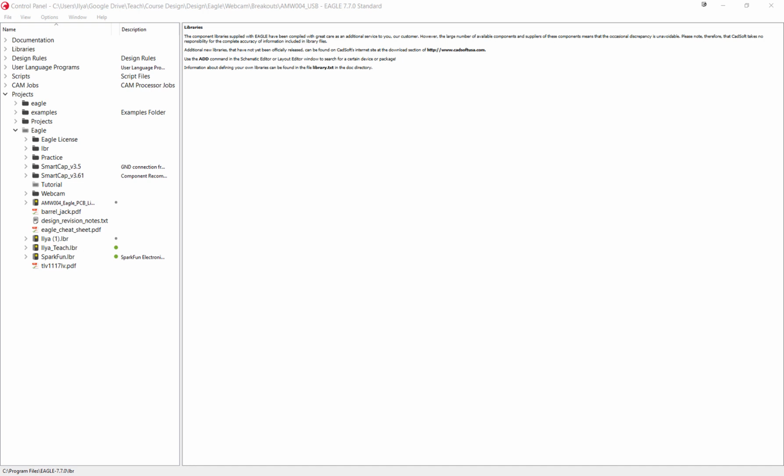A breakout board is a useful hardware tool. It gives you access to all the pins of a package that otherwise would be inaccessible. When you have a through-hole dual inline package, you are often able to put that directly in a breadboard and therefore prototype easily. However, if you use surface mount components, this will not be the case.